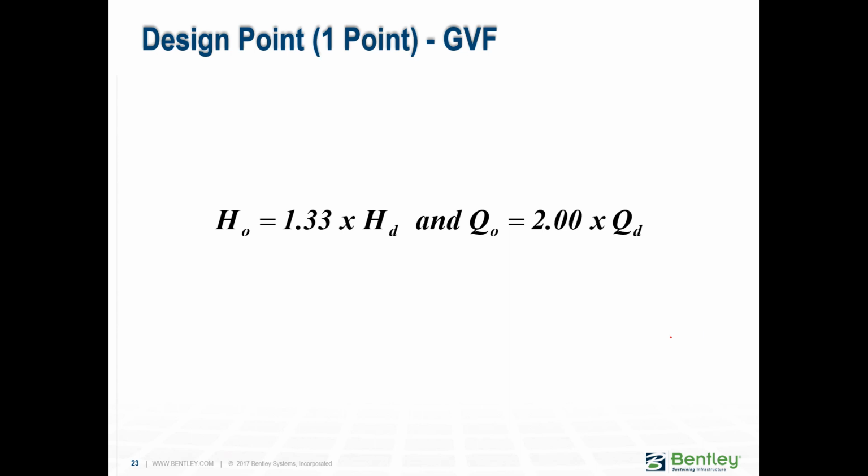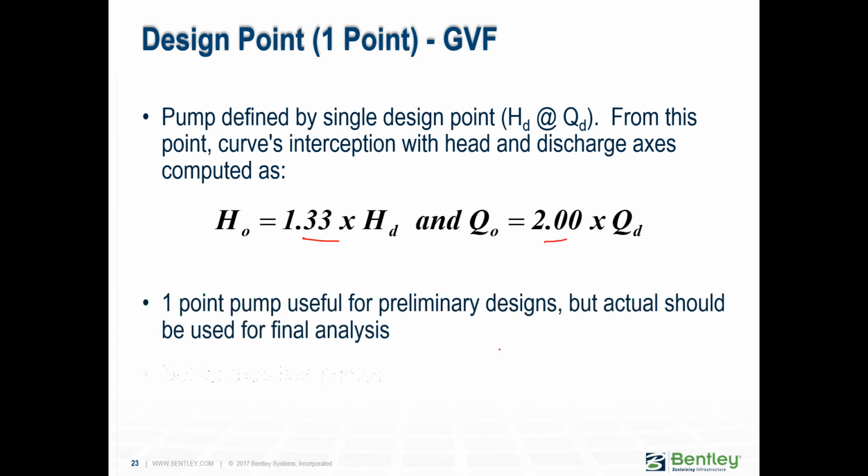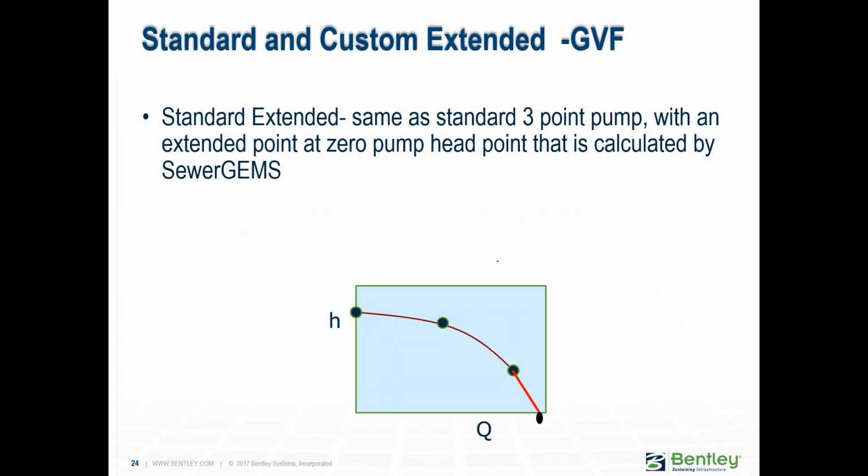So how did SewerCAD come up with all those points? Well, those values that we were looking at come from a full set of equations. But this comes from a typical pump curve, so it's pretty standard and accurate. So if you do go with this, then it's okay for the original design, but once you've decided that that is the design point that you want, then what you want to do is go to the manufacturer, get a real catalog, and input all the points along the curve, not just stick with the 1 point.